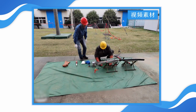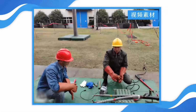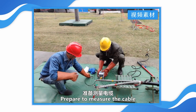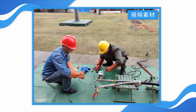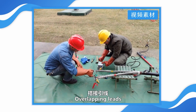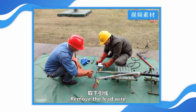Megohmmeter E terminal to the grounding wire. Connect the shielded wire. Prepare to measure the cable. Measure the A-phase cable first. Connect the L lead. Shake test for 1 minute. 2500 megohms. Remove the L lead.